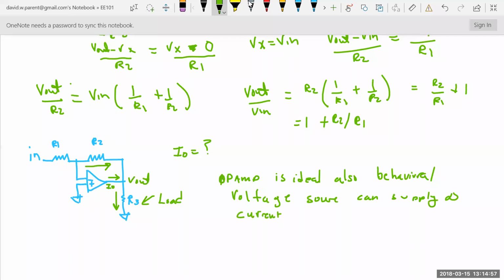infinite current. Sure, there's a node here, and you might think, oh, I've got to do a nodal analysis here, and now I have to do a nodal analysis here. But you don't really. V out is something times the difference here. So there's really only one node that you don't know, right? Because you already know what V in is, you know what ground is, and in a sense, you know what V out is because it follows what's going on here at node Vx. So in fact, R3 doesn't affect V out. You don't have to do a nodal analysis for it.